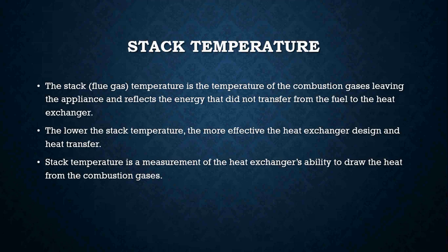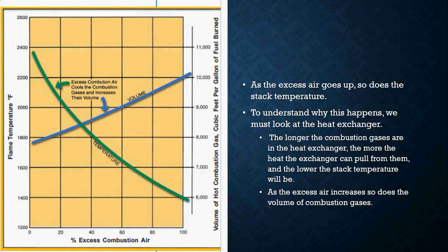Your stack temperature, or flue gas temperature, is the temperature of the combustion gases leaving the appliance and reflects the energy that did not transfer from the fuel to the heat exchanger. The lower the stack temperature, the more effective the heat exchanger design in heat transfer. Stack temperature is a measurement of the heat exchanger's ability to draw the heat from the combustion gases. That's why we take these readings.